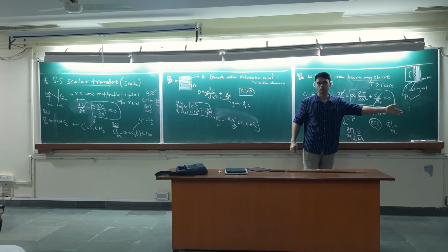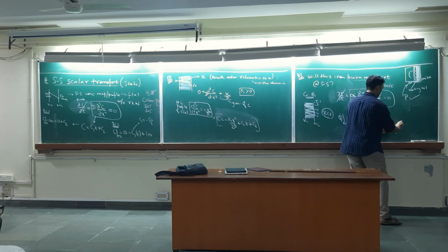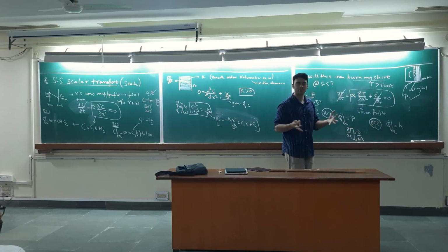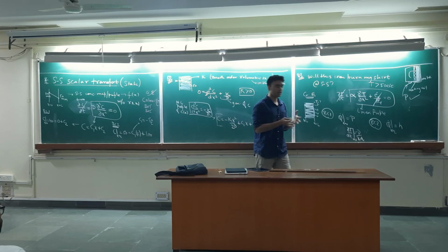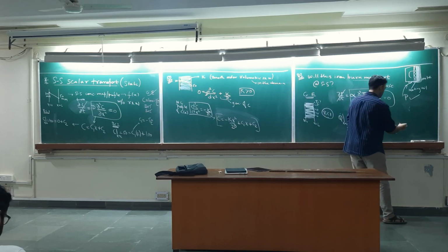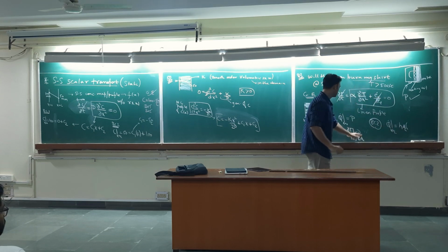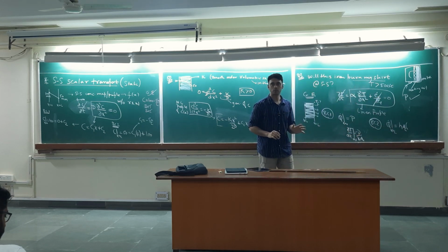What should it be equal to? Convective, na? Conductive, we'll have here, equal to hA. Because otherwise, if it's not equal, then there will be some buildup on the interface. So whatever has come until this boundary has to leave from the other side. So this is Q dot equals hA_c, and this A_c and this A_c will be the same in this case. Rectangular geometry: cross section and the outside is the same.